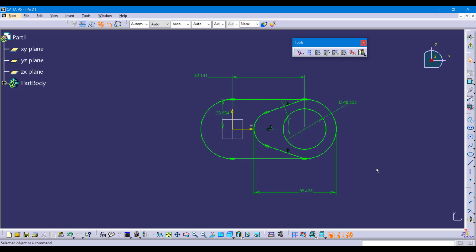So again, traditionally CATIA would yell at you if you were to try and create a pad feature from this singular sketch, because CATIA would not find a closed entity. What we need to do with our output features is to tell CATIA within this same singular sketch to segment our different shapes out. To make that segmentation, we are going to utilize those output features here in the Tools toolbar. To start off, I am going to begin with the circle.